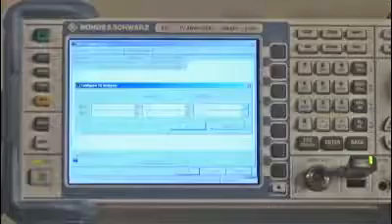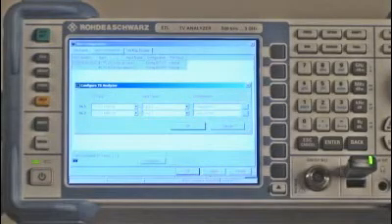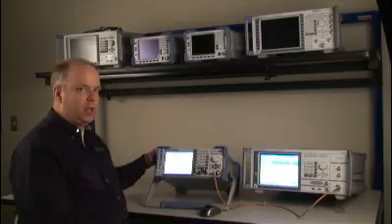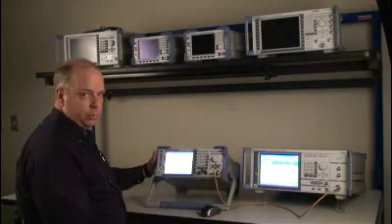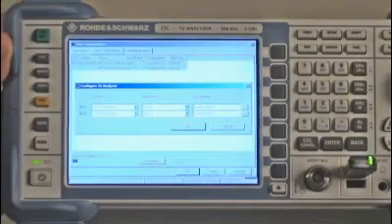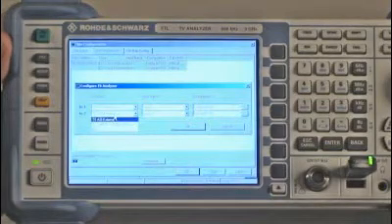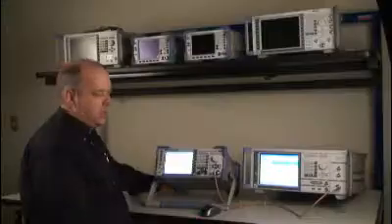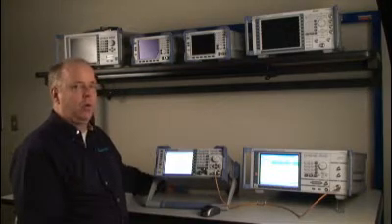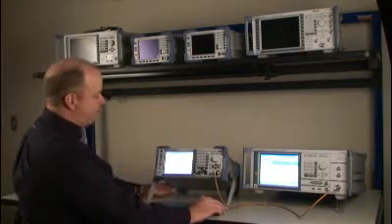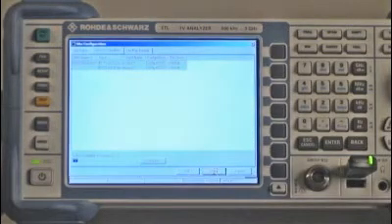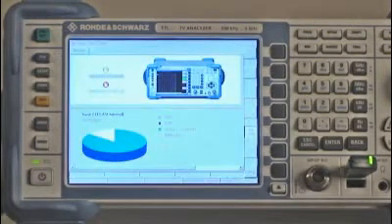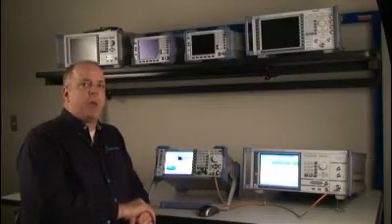So as you can see here, I'm set up to ASI internal, that is demodulating the RF from the 50 ohm input, which we talked about earlier. And on the second one is the external, which is the ASI input on the rear of the unit, which I'm not going to be using in this case. Making sure that it's all set up for ATSC, and then selecting OK, Apply, and then OK. So now I'm ready to start my measurements.